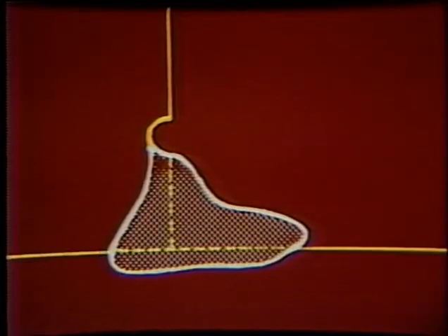The next type of discontinuity related to shape, size, and contour are welds with incorrect profile. Discontinuities falling under this category are undercut, overlap, and underfill. All of these discontinuities can alter the strength and appearance of a weld.